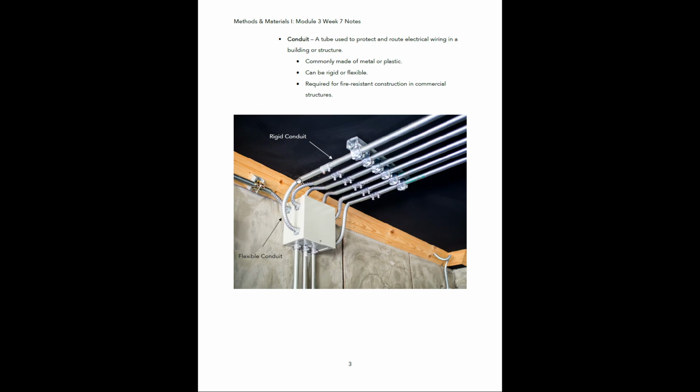And then these are meeting up with flexible conduit. So you can see this is actually a metal sleeve that is bendable. Okay, so this can bend and it can move in a bunch of different directions. You might also use conduit in situations where you have to embed it, like into concrete. So if you have concrete panels or a concrete slab that you have to run electrical through, you might embed the conduit within the concrete. All right.